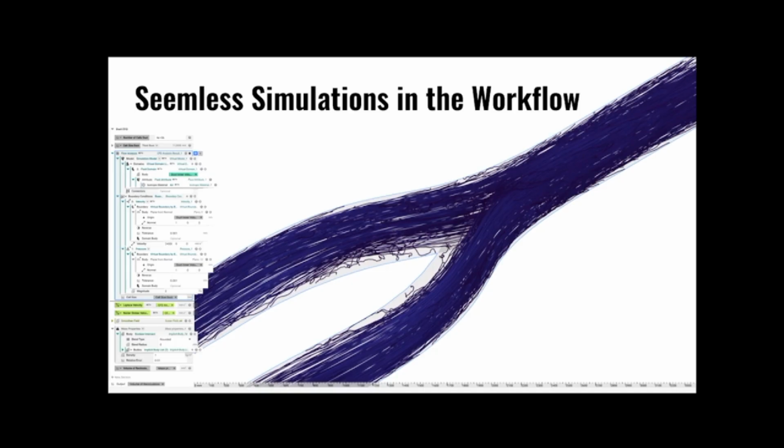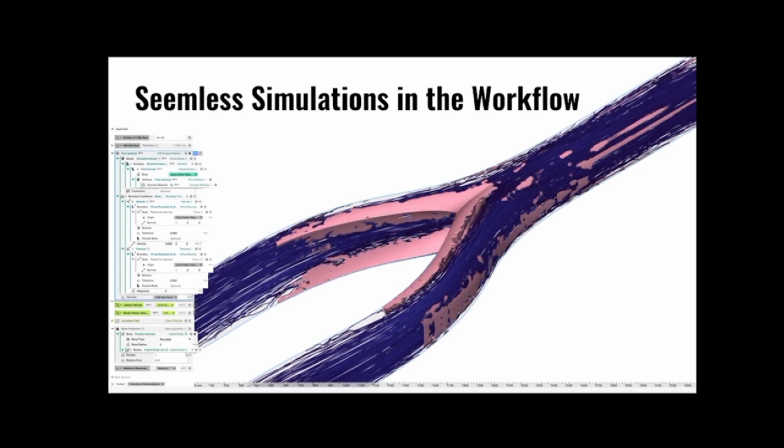We define the fluid to be air, and the only numerical parameter left to state is the voxel size. And we have good practice for that, how to choose that. And from one of these simulations, you can extract recirculation areas or separated boundary layers.